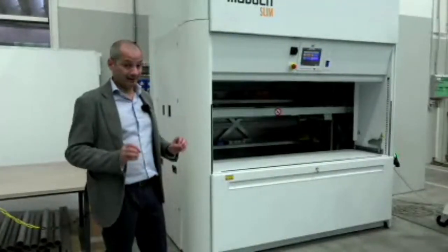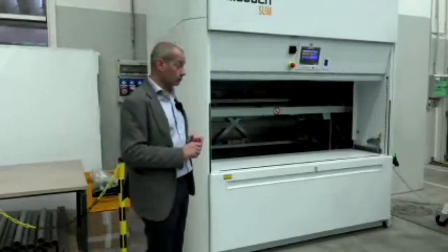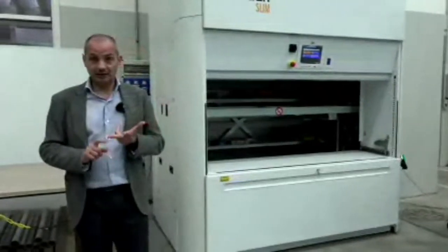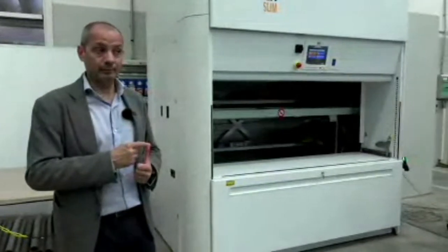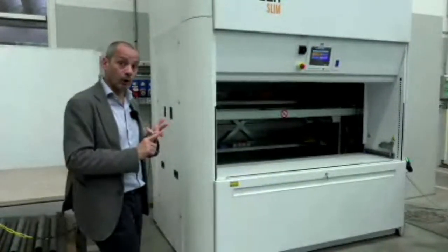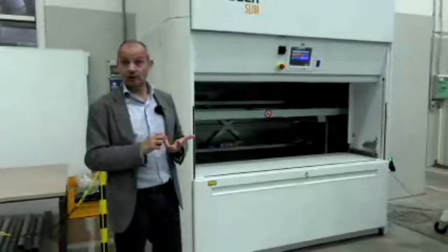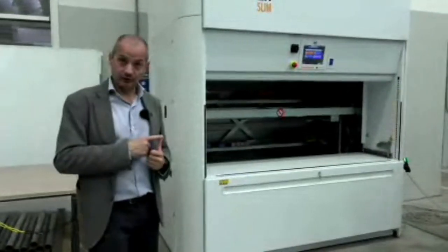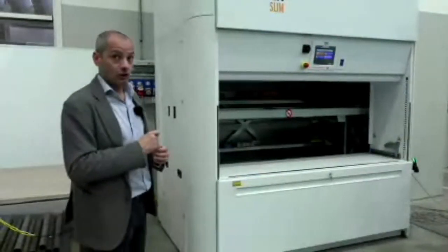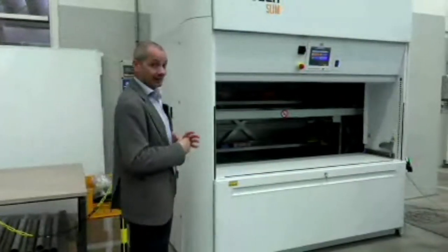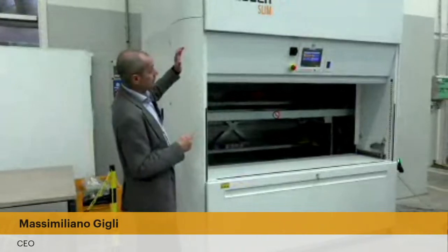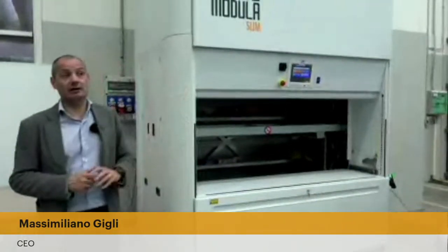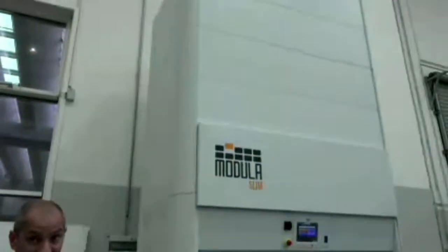Just a couple of characteristics before giving the word to Gianluca. Three types of tray with three different widths: 1.3 meter, 1.9 and 2.5 meter. One single depth, 420 millimeter. One single payload, 350 kg. Anyway, a very good payload for industrial application. Different heights: in this case, we start from 2.4 meter and we go up to 7 meter.